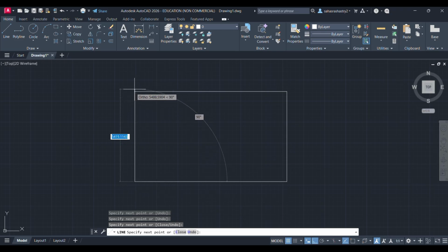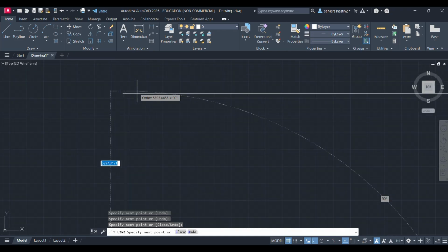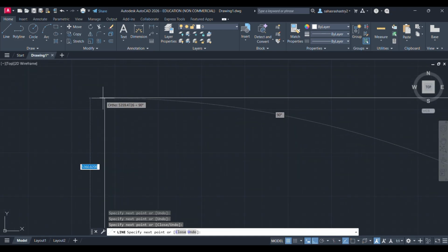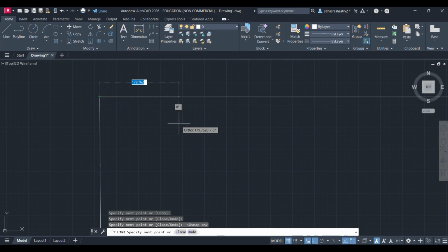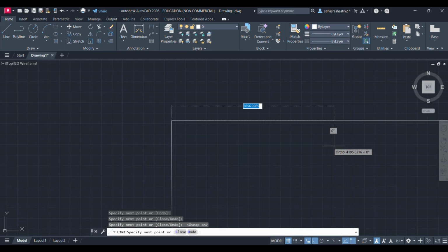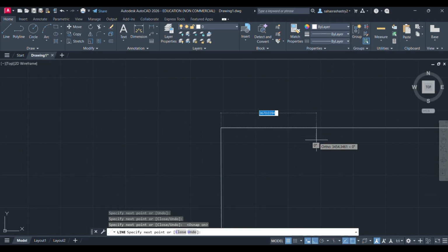See, here nothing is shown so that you can exactly coincide and draw a particular rectangle. But when you turn on OSNAP, see here, it highlights the intersection point or specified endpoint so that you can easily catch it, right?